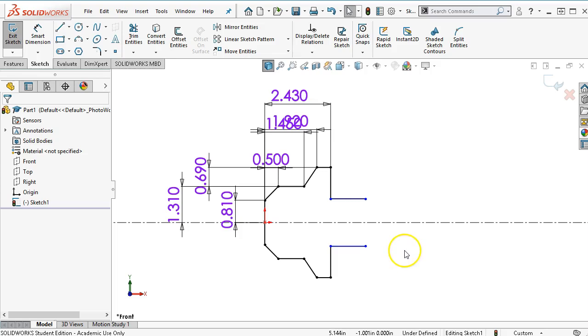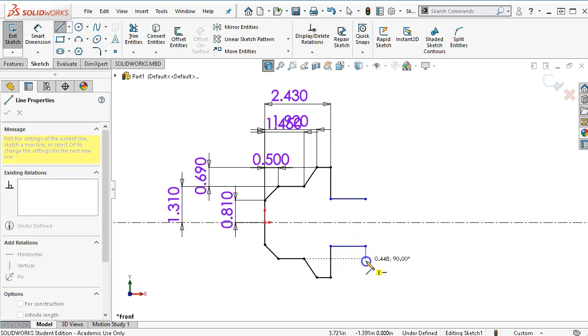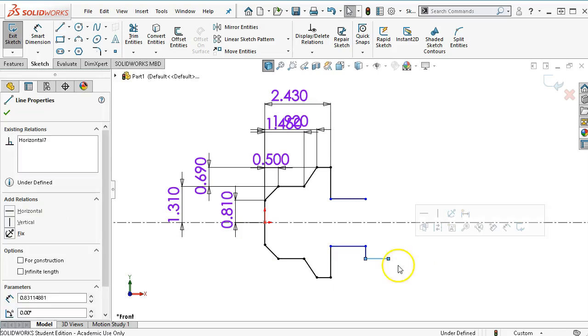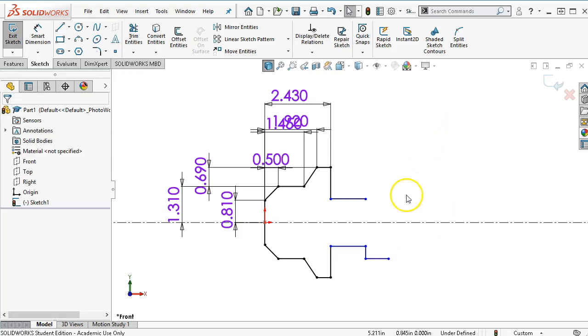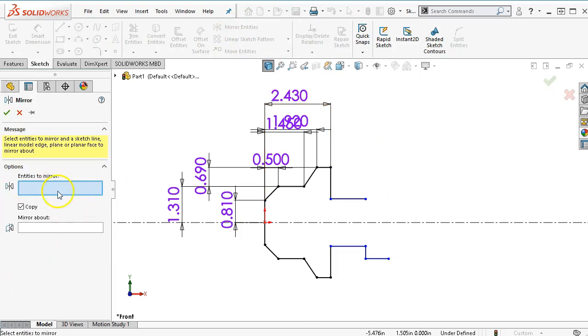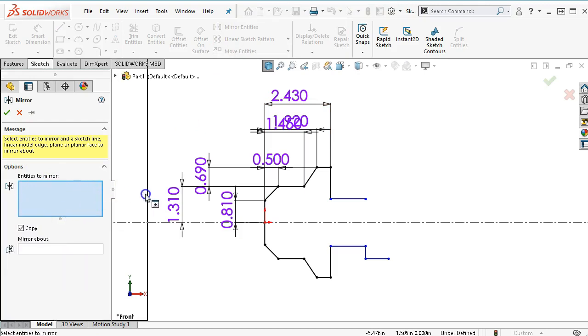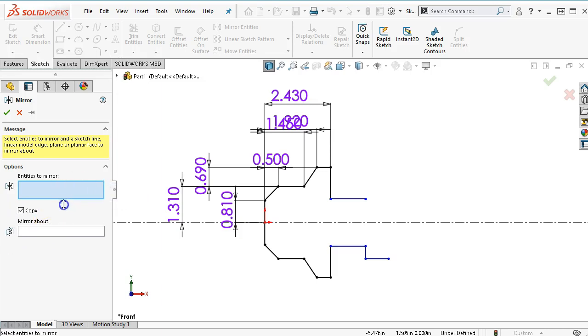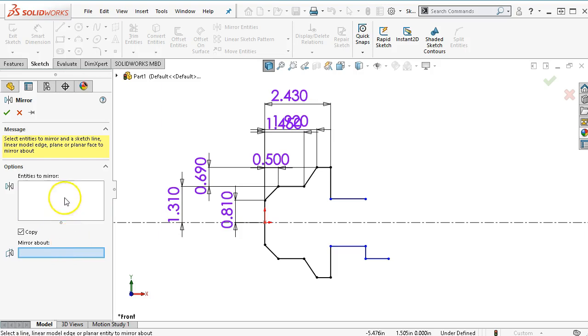Alright, so my dimension, we're going to need a few more steps since this dimension's from the steps back. And actually I wanted to do one more before we got into that one. So let's take those two segments and we'll go into mirror entities. And so now nothing is selected. Wherever you see the little dots, that's going to allow you to drag. So dot, dot. And so if you've selected enough items and it's kind of outside of the window, then you can stretch that out and get a few more.